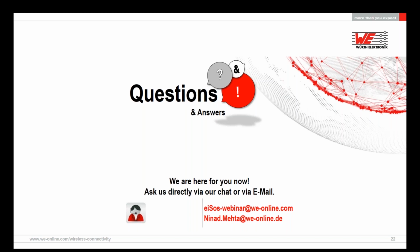Ninat, I see the first question has come in. Can I use the differential pressure sensor for liquids or fluids? Unfortunately not. The differential pressure sensor is only compatible with clean, dry and non-corrosive gases. Liquids will surely damage the sensor and the sensing element as well. However, small particles are allowed as far as they do not block the pneumatic channel. This might also have some effect on the accuracy. For what kinds of gases can be used with this sensor, please refer to the user manual.